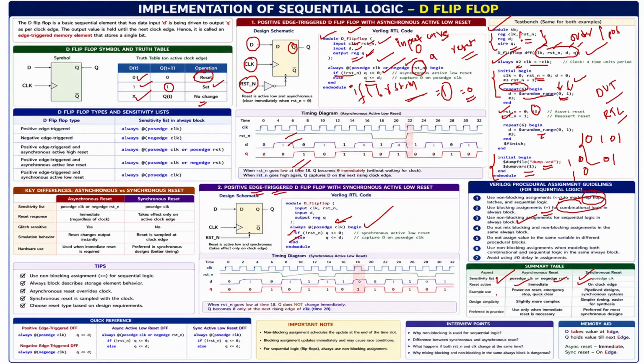As an example, if you want to reset your program, you can stop any program and then go for the reset. In between, we have operated the reset, right? At this condition, I am resetting and I want to go to the initial condition. At that time, reset will be used. For power off conditions and emergency stop conditions, we use the asynchronous reset. And the clock edge is used for pipelining operation. That means one clock is executed, then the next clock is executed. Whenever the posedge of the clock is there, at that time your simulation will be executed.